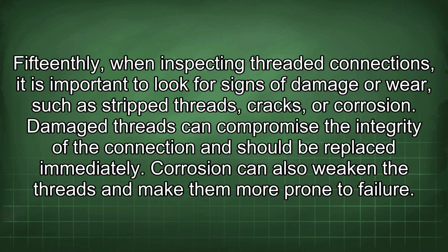15thly, when inspecting threaded connections, it is important to look for signs of damage or wear, such as stripped threads, cracks, or corrosion. Damaged threads can compromise the integrity of the connection and should be replaced immediately. Corrosion can also weaken the threads and make them more prone to failure.